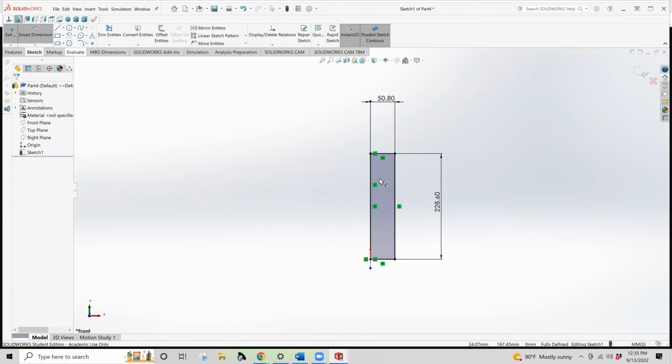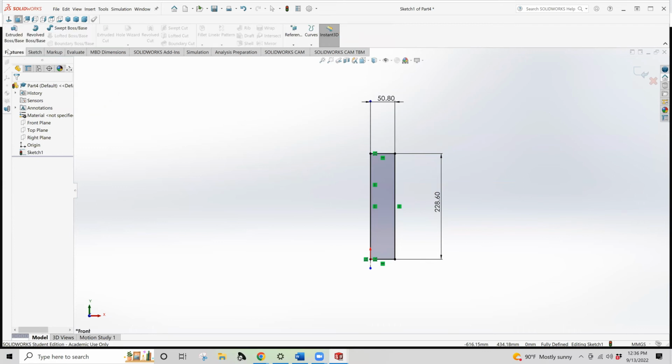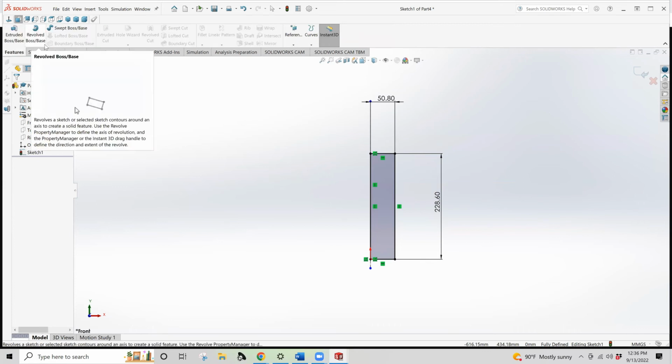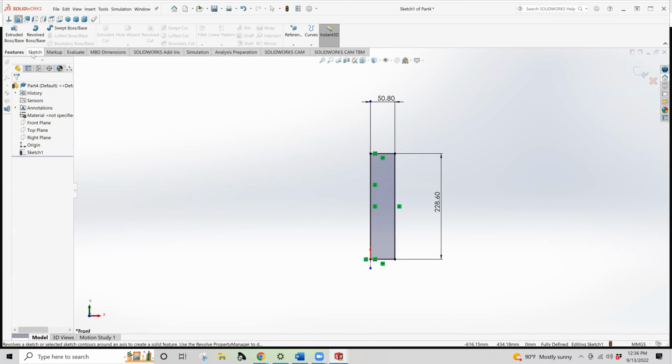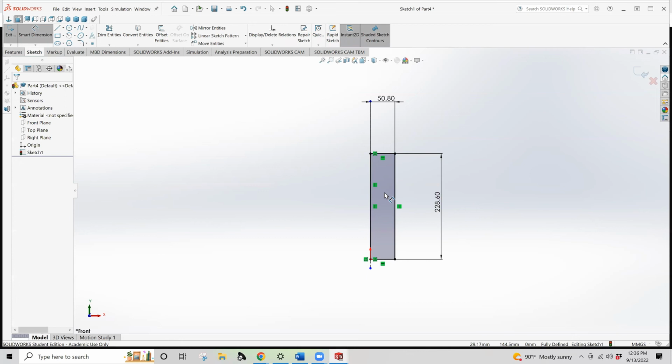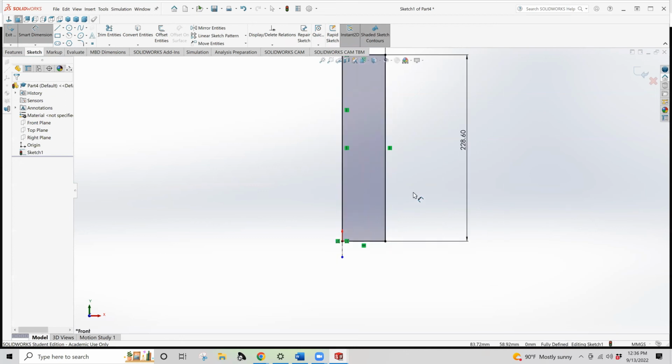Then there's going to be some additional geometry we'll need to build in here. So this is kind of our rough exterior geometry. There's a couple kind of interesting things that we can do from here. So I'll show you some examples of both. One is we can use, I guess, one more technique that we haven't used yet. So I'll do the inverse. Yeah, that'll be, I think, an interesting way to do this. We'll do an inverse and do a revolve cut, since we haven't seen a good example of that. So a reverse cut or revolve cut.